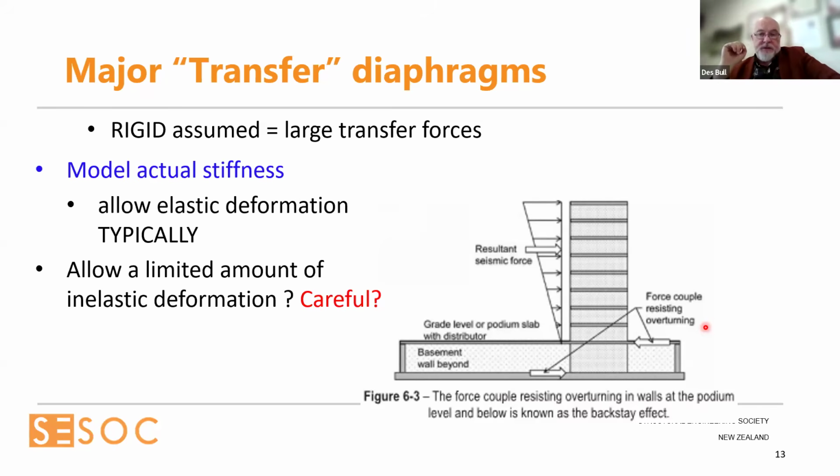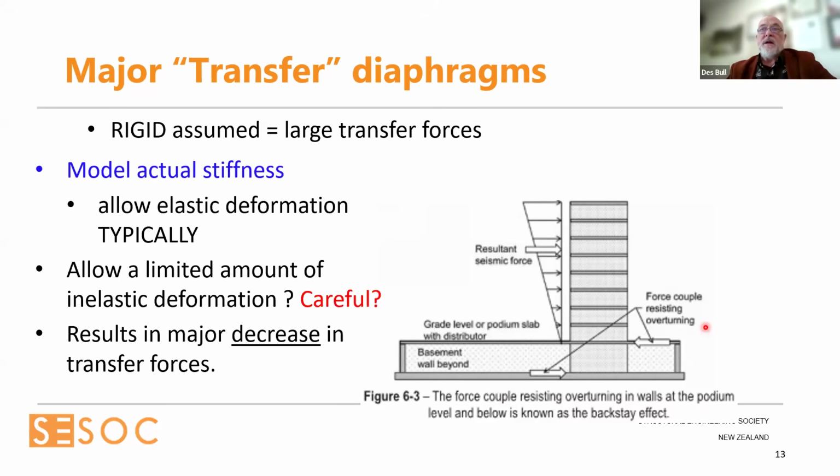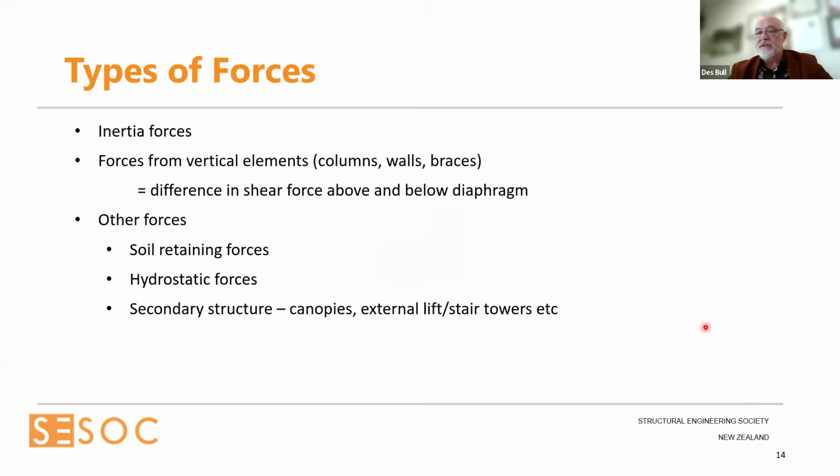Some people have talked about using plasticity in the diaphragm. Not recommended at all. If your diaphragm becomes plastic, that relationship between the vertical systems changes and can be quite dramatic. So by modelling your actual stiffness, you can actually result in a significant reduction in transfer forces, which is good for the whole process.